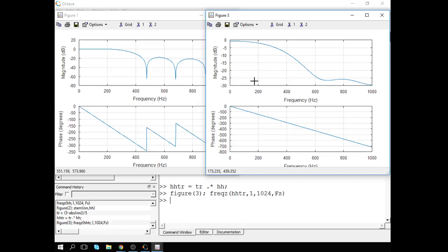The smoother the window is, meaning the less power on the high spectral components, the more attenuation you have. It's kind of natural, since most of the power of that smooth window is on low frequency components. But it also means that our transition bandwidth is now wider. So it also has effects on the transition bandwidth.